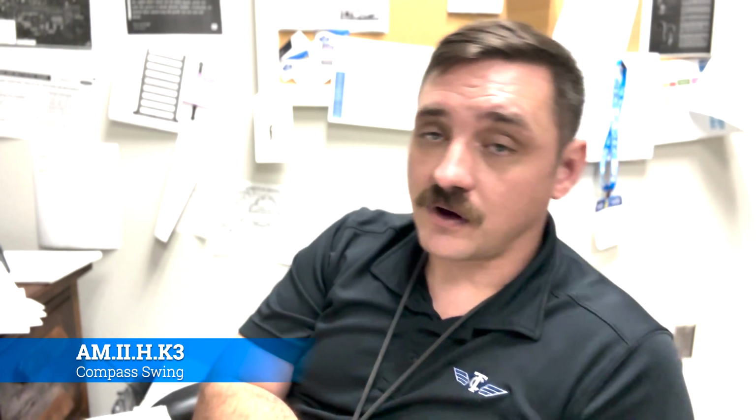All right, number 2 is moving parts of the compass should work easily. Now you would think that the compass doesn't have a lot of moving parts, but it actually does. It has little set magnets in the bottom of it that we're going to talk about here in just a second. But you should also be able to rock the airplane and watch the dial spin. If it hangs up or gets kind of cattywampus or something like that, then you probably need a new compass. They're not really that expensive. They're pretty simple devices. So don't just deal with something, fix something.